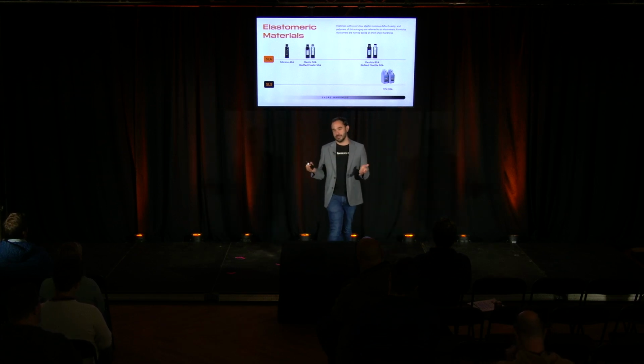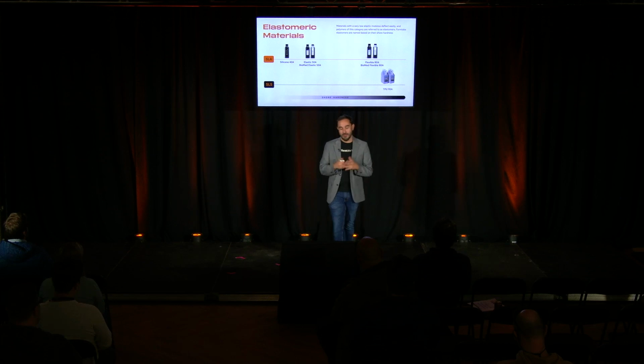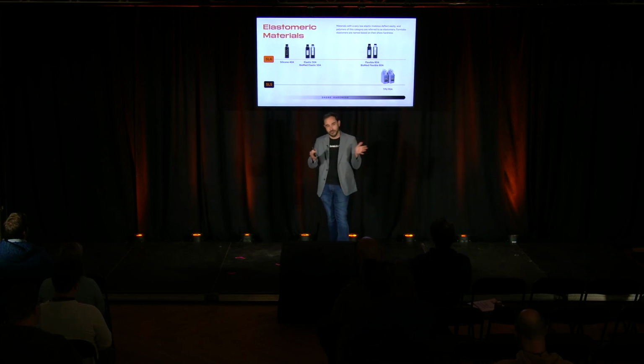And we measure this with a Shore hardness gauge, is one common way that we do this. You're just pressing into the material and measuring the response. So it's basically an artificial scale. We're typically using the Shore A hardness scale. And you'll see that all of our materials are labeled with their Shore hardness value on the material. So our least soft material is TPU 90A, and that has a Shore hardness of 90A.